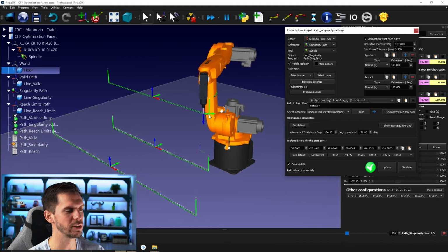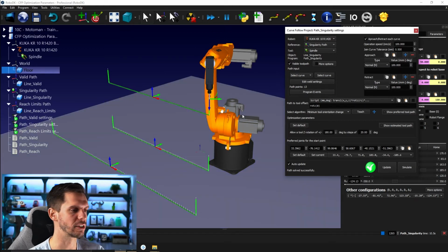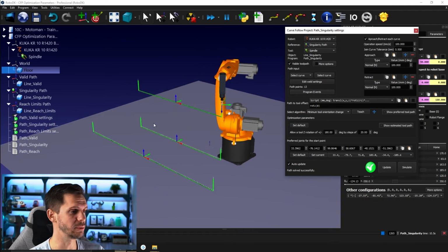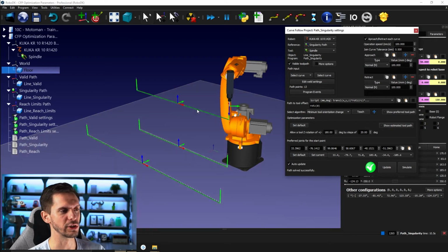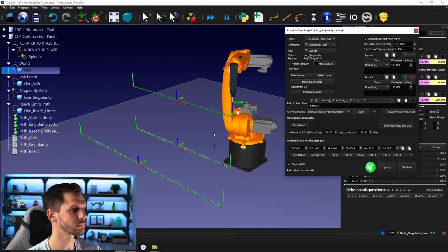So I will have my 20 degree rotation from one point to the other. So it's super smooth as a rotation, but I have a bit less control on when it's happening. So that's something I can do. I'm going to show you another example where you can split the curve here and do your translation or rotation here, and then do another straight part here. There are ways to go around that.